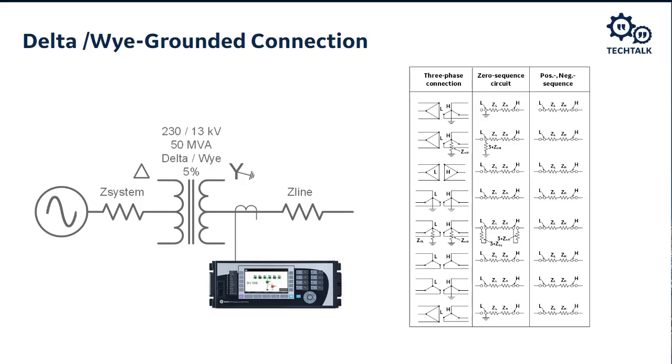The delta connection on the primary side, though, that's going to block that ground fault current, and we want that. And the reason we want that is because we don't want to have to coordinate on our 230 kV transmission system with our relaying down on the distribution system. We don't want to have to coordinate for those faults. We don't want to see all of those ground faults on our transmission system and affect the power quality of our transmission system. So that delta connection does something very specific for us.